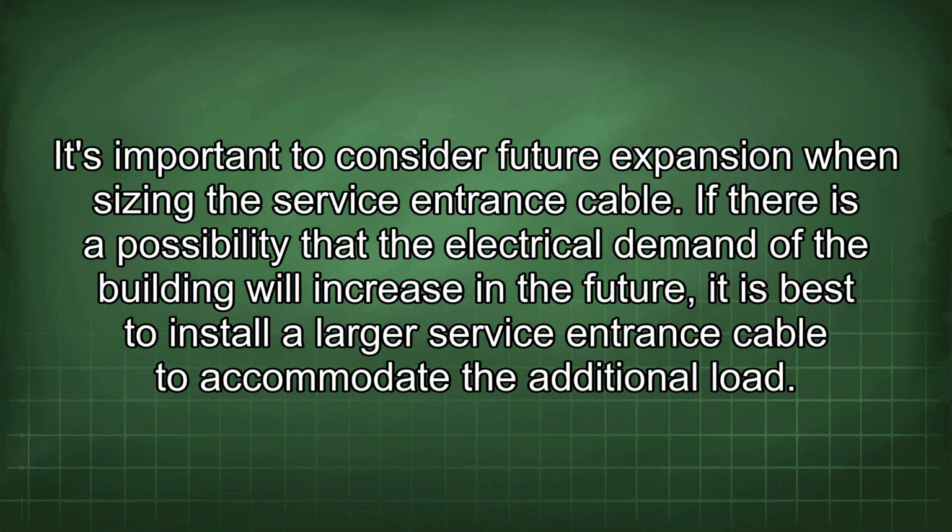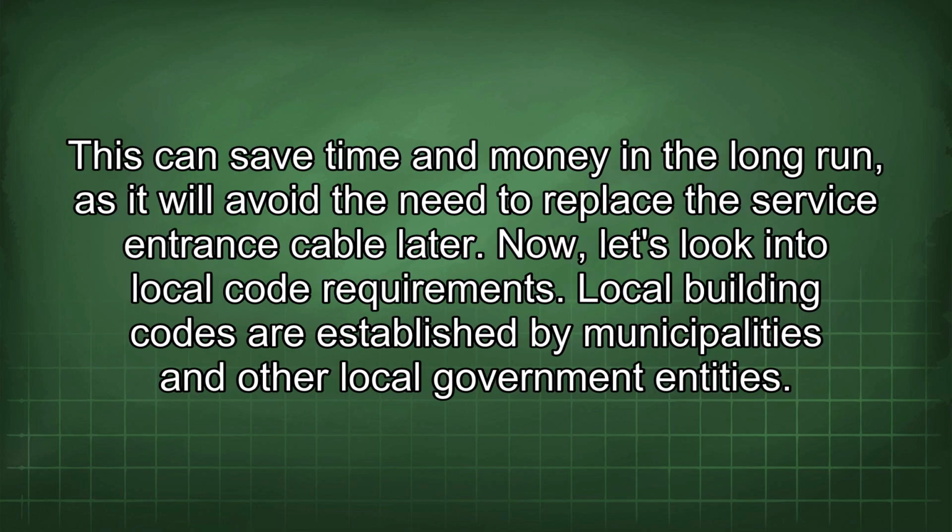It's important to consider future expansion when sizing the service entrance cable. If there is a possibility that the electrical demand of the building will increase in the future, it is best to install a larger service entrance cable to accommodate the additional load. This can save time and money in the long run, as it will avoid the need to replace the service entrance cable later. Now let's look into local code requirements.